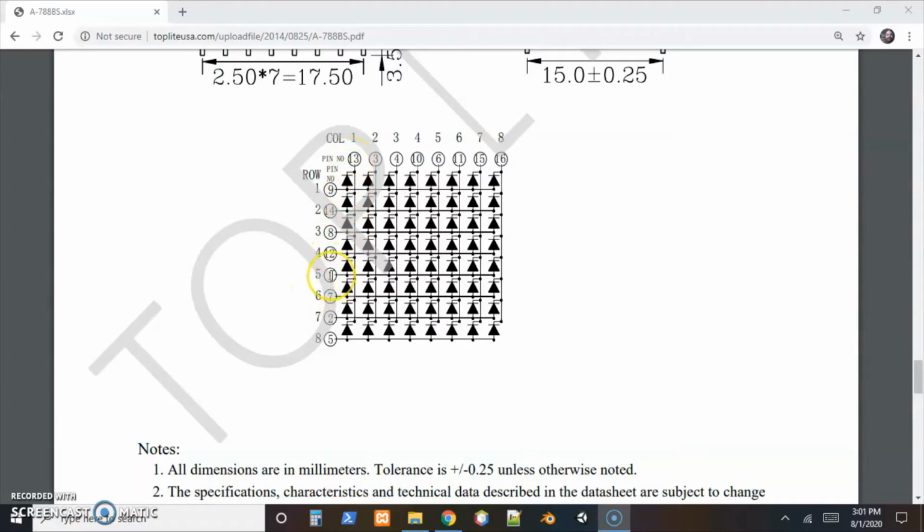So I picked a corner, counted around to what should have been 13, stuck a resistor back to ground, and sent 5 volts to pin 1 to see if the correct row, so column 1, row 5, came on. It did not on my first attempt, but it did on the second. So then I picked another corner, repeated that process, and it worked on the second corner.